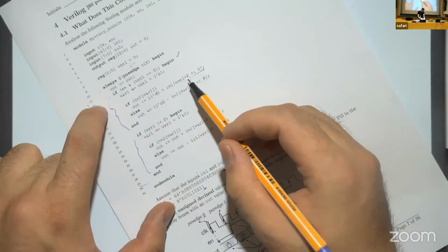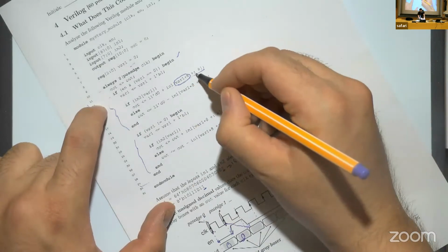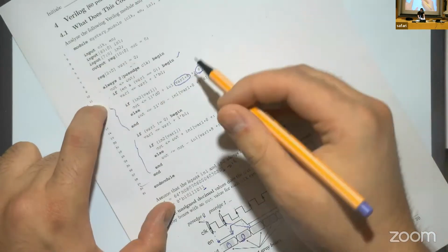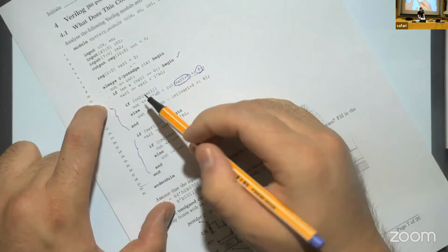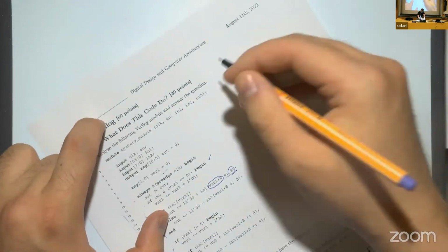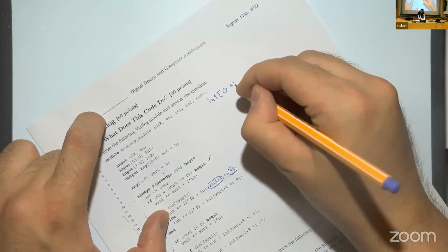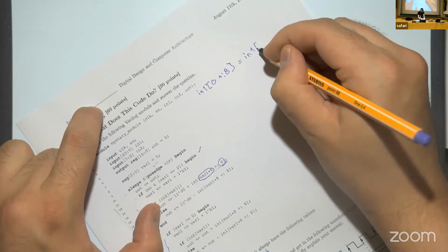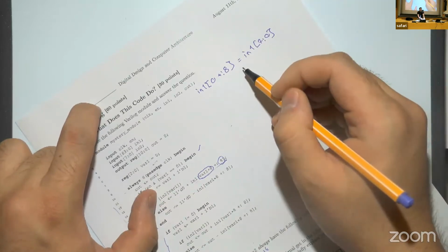This means that this is the base, and this is how many bits you'll count afterwards. So let's do that with an example. We know that variable 1 is still 1 here. What that means is, maybe I can write here, in1[0 plus 8], which is equal to in1[7:0]. So you start from this space, and you count 8 bits.